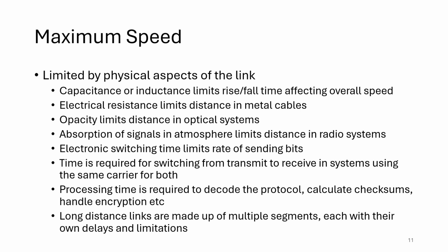There are, of course, electronic switching limits, but the amount of time you can send a bit is limited by the switching time of a transistor. Generally, that's not one of the issues in modern networks. It's normally one of these previous limits on the actual physical media, but on very short but very fast networks, electronic switching time does become an issue. Transistor sizes are shrinking, and as transistor sizes shrink, there's less resistance and capacitance in the system, which is allowing faster switching times. But the technology is taking time to get there, and at the moment, the electronic switching time is the ultimate limit for us.